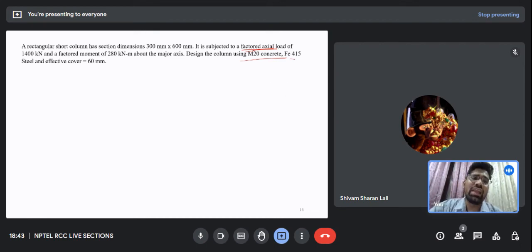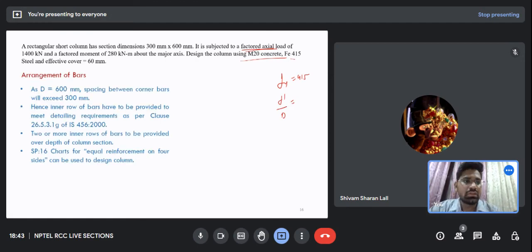Firstly, what will I have to do? I will have to check fy. Okay, it is 415. Now what will I have to do? I will have to check d dash by D. See, d dash by D, I can check it. Now d dash by D, what is it? Just quickly tell me. 60 by 600. So it is 0.1. So from these two I can select the chart.